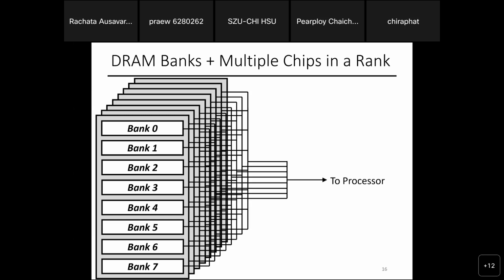So that's like your typical CPU. Modern day DRAM that goes into a GPU, for example, looks different now. It's because you have stacking, and you have metal, we call it through silicon via, that sticks through the whole thing. It's like when you have layers of DRAM and you push the metal stick through all of them. And because you have a 2D surface, you can put a bunch of these metal. Now you have way more bandwidth. DDR5 is more like this. But high bandwidth memory that's used in, like, the A100 GPU will look more like the other one I explained, that has DRAM on top of each other.